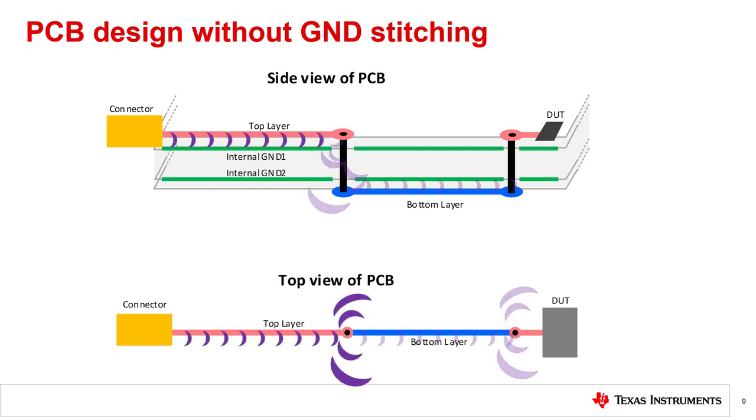You may be thinking that your system has only a 50 MHz clock, so how can we get high frequency emissions? Don't forget that the Fourier series of a square wave showed frequency content into the gigahertz, and the waveform rise time determines how much high frequency content you will have. The point of this slide is to emphasize the importance of stitching vias to provide a continuous waveguide for signals to transition between layers.